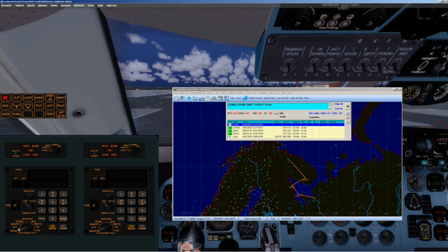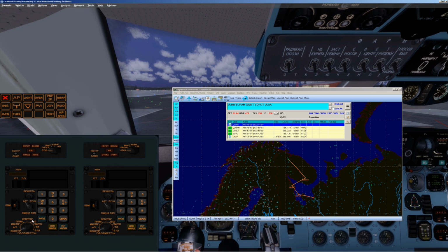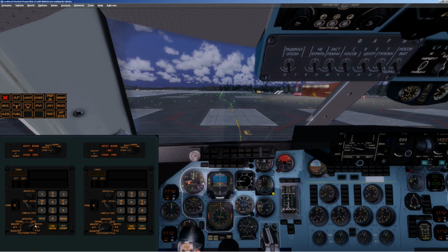The secondary selector has 9 positions: control position, aircraft coordinates setup position, control alignment position, point-to-flight programming position, bearing and course position, position of the coordinate system, ground speed and slip angle position, and time position.